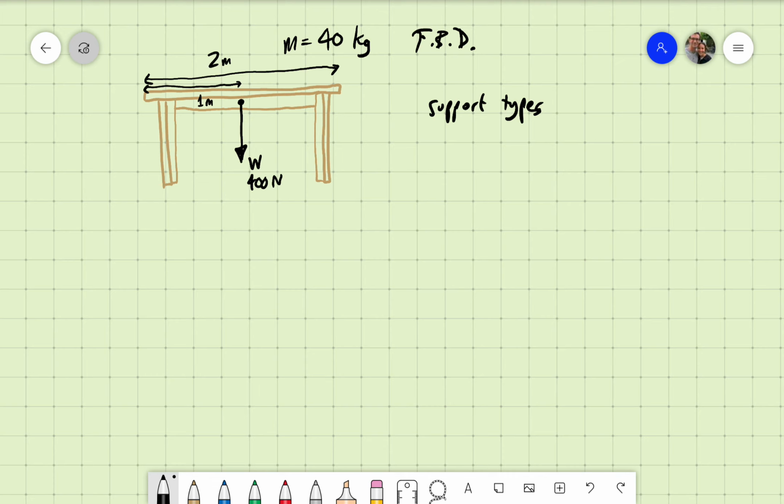This is like the tent pole. It's like the crate just resting. It's just simply sitting on the ground. So the simply supported type, SS for simply supported, only has one possible reaction. And it's this one here. I'm just going to say R1, R2.